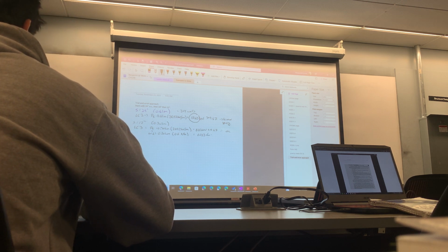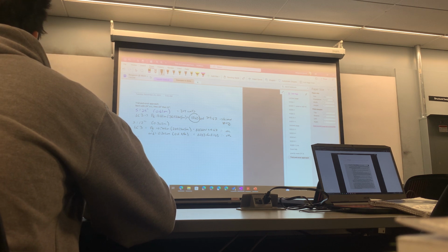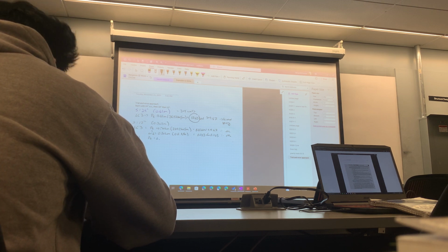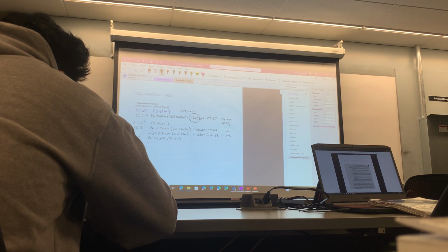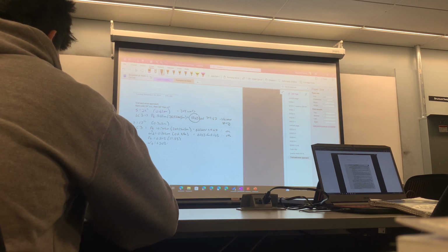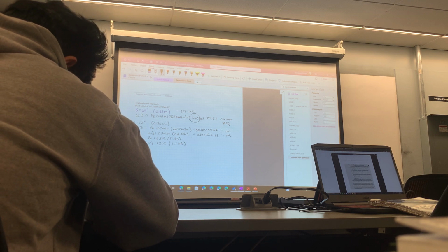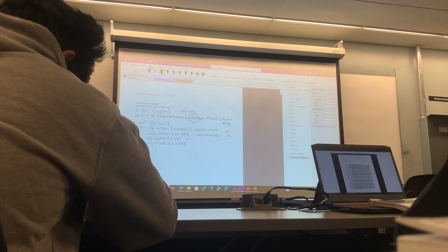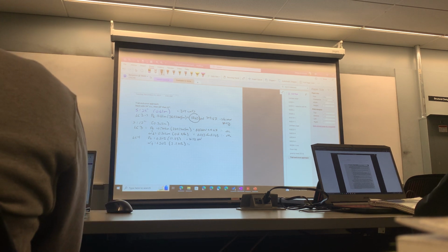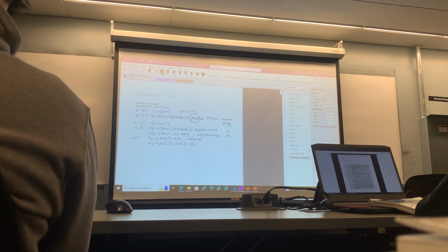Now we've got to check load case 4. For load case 4, you've got to do PF again. This is going to be the lower PF, so this is 0.302 times 13.83. And then your W prime F is going to be 0.302 times 2.1. Now the wind governs in this case. You're going to have 4.22 kilonewtons for PF. W prime F is 0.64.